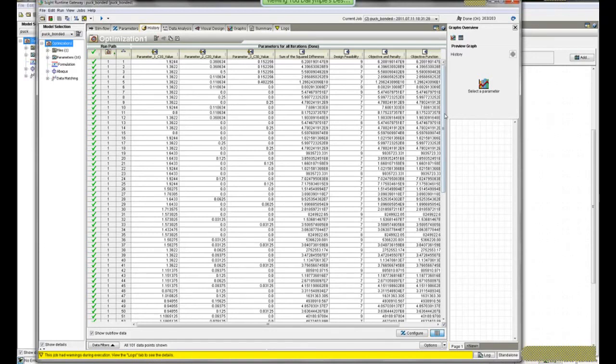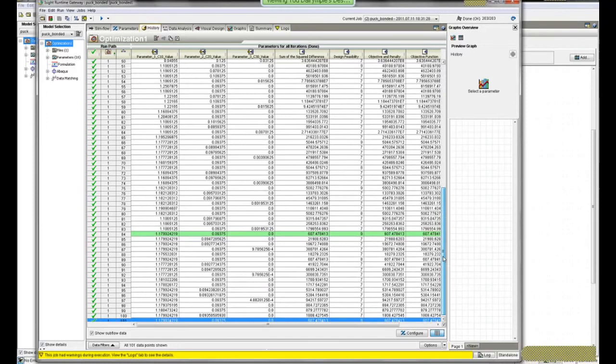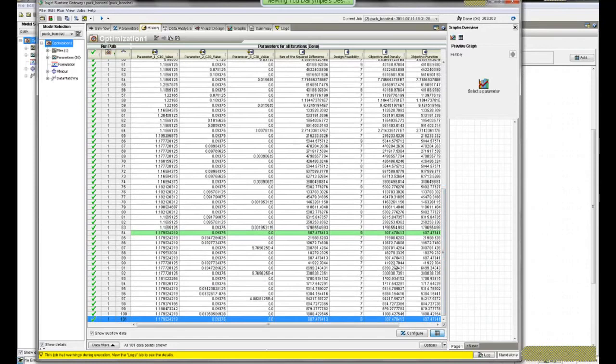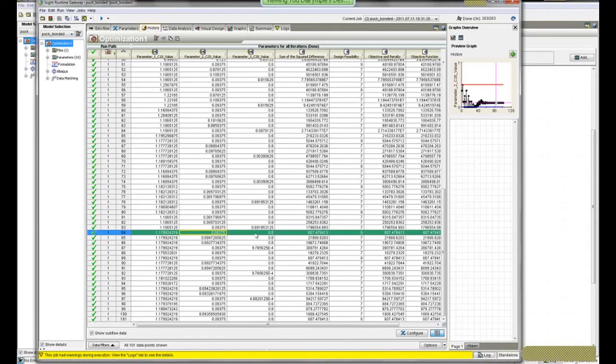As it goes and goes, it's going to do a default max number of 100 passes through Hooke-Jeeves optimization. The lowest it achieved was a sum of the square difference of 607. In fact, these values of C10, C20, and C30 are the ones that I showed you in the PowerPoint, and they match up very nicely. That's one way of looking at the history of things.